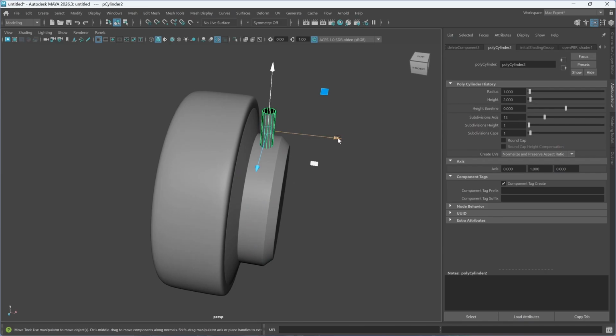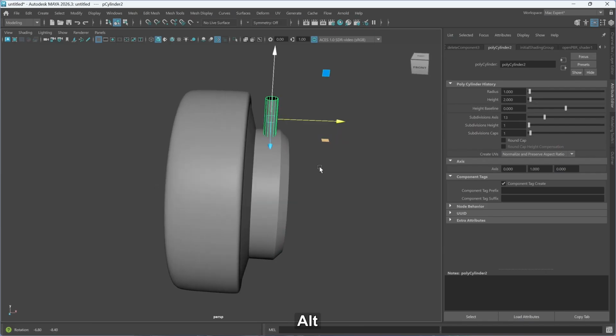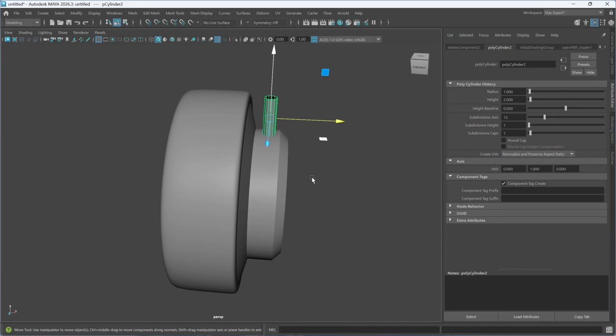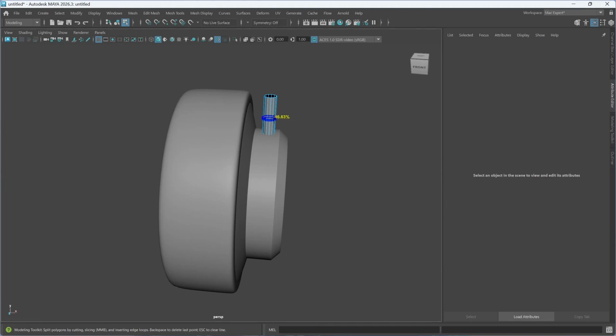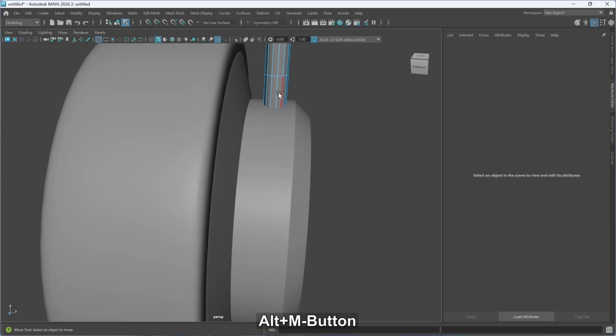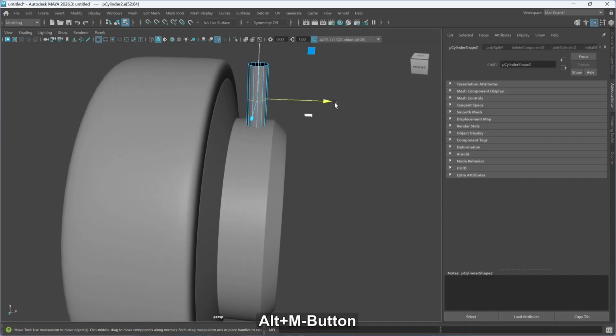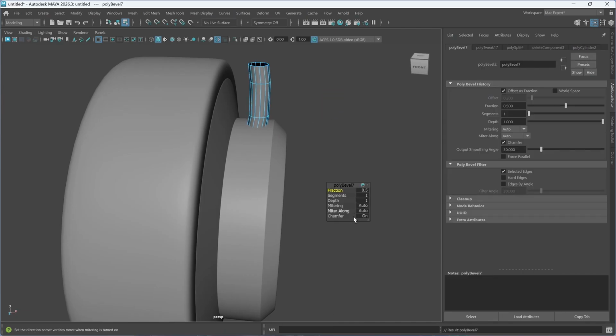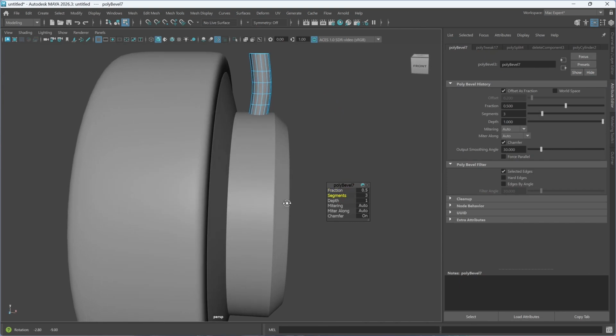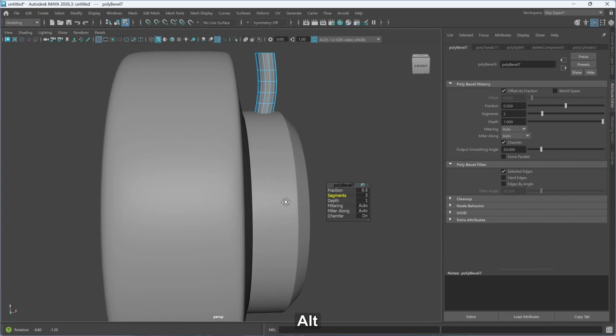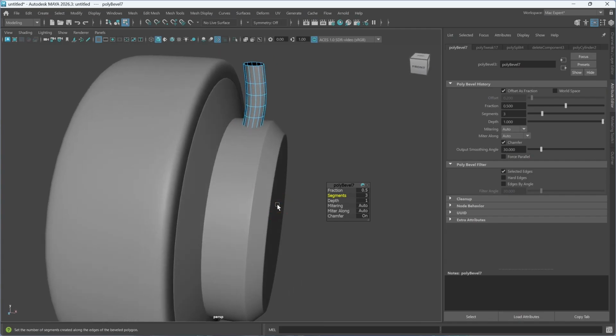Now we can select this. Yeah, so we need to make that curve a little bit. So go in and hit M, select multi-cut. Add a loop in the middle, hit W, select that edge, take it backward a little bit, hit Ctrl B to bevel, add 1 in the middle, so we need to make this smooth completely. Not that bent, we shouldn't make it that bent.